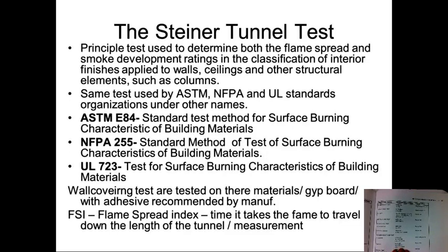So when we talk about the Steiner tunnel test, it's a test to determine both the flame spread and the smoke development ratings, because remember we said that the number one killer in a lot of fires is smoke and inhaling the smoke. So we want to make sure that we look at both of these things, not just the flame spread, but the smoke. Some of the same tests are used by the ASTM, the NFPA, and the UL standard organizations under their names.